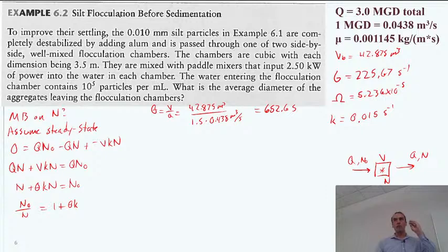Now here's where you have to apply what you know, right? Because we first of all think to ourselves, okay, it's continuous flow and it's being mixed. So it should be a CSTR, right? If we look at the system, we ought to recognize that's a CSTR, and that's why we're building the mass balance this way. Now the reaction term we also have to think about because we're maybe not sure exactly what reaction order this is working in.